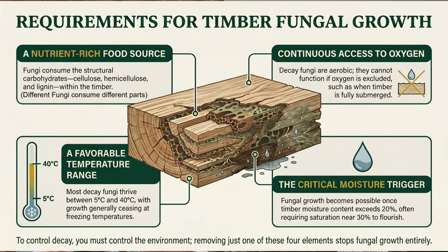And as we've probably noticed outside in our garden space, if you've got a tree that's fallen over in your garden, it takes a heck of a long time to rot, but it rots from the bottom. It rots where essentially you've got that persistent moisture and it can't dry out. So what we have is what's sometimes referred to as the Goldilocks zone, which is where fungi need the perfect balance of dampness or persistent moisture, that's oxygenated, so access to oxygen so that it can still thrive, and it needs to be a certain temperature with the food source that we've covered. If you have all of those, then you've got the conditions for decay of fungi.